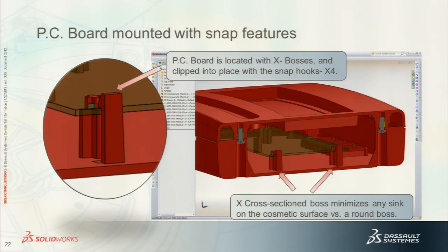I do not have the material costs of the 4 screws, and you don't have to support the inventory for the screws. So it is a cost. You pay for these features up front in the tool, but you save money in the long run because you do not have to support using the screws in the mounting of the board.